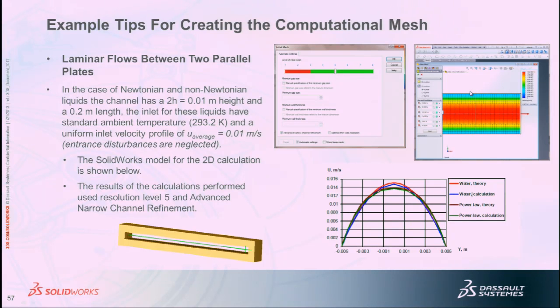And you can see the mesh refinement in this region. This is a velocity plot. You have the walls. And you didn't really need a very graded mesh towards the walls. You could see that the mesh is not infinitely small to get the right result. We were able to use fairly large cells in this particular case and still get results that match very well.